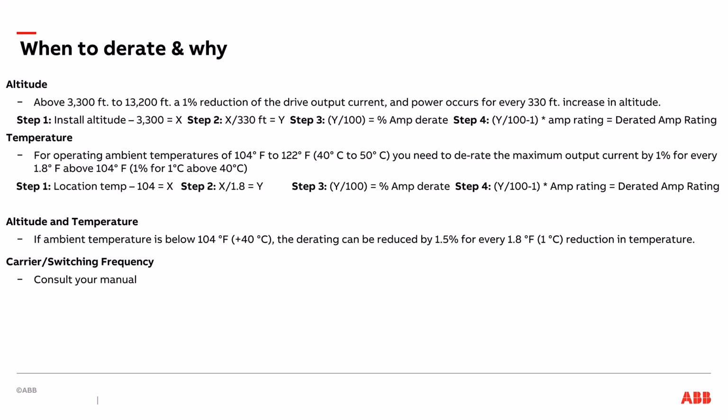There are other solutions, such as having the drive monitor the heatsink temperature and automatically reduce the carrier frequency as the temperature increases to avoid overheating, but this needs to be evaluated for whether it's appropriate for the application you're supporting.